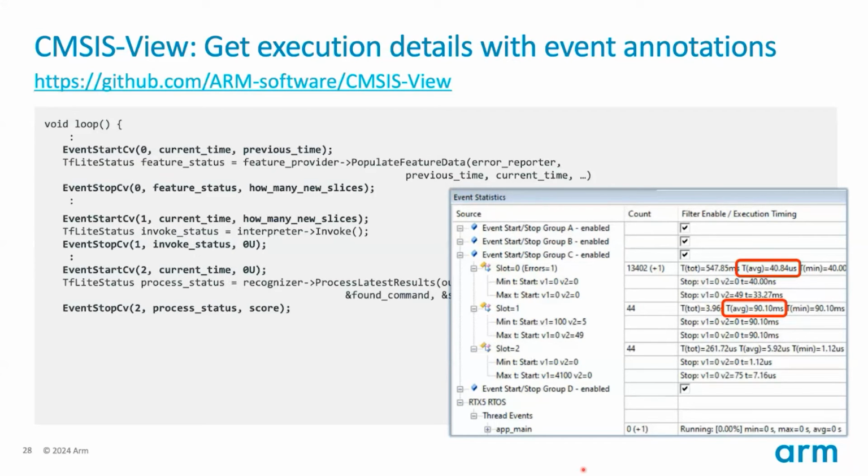One tiny caveat, or let's say one thing you have to pay for, is that this event recorder technology is using a small amount of your RAM, where basically the event recorder data is written into this RAM, and the debugger continuously reads that RAM and transfers the data to your debugger.